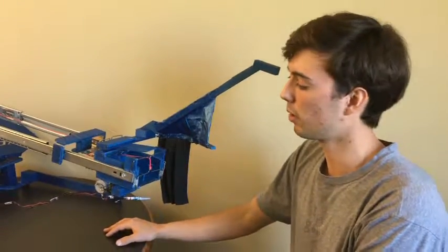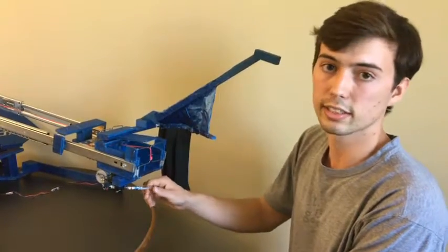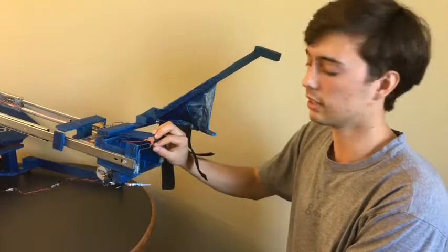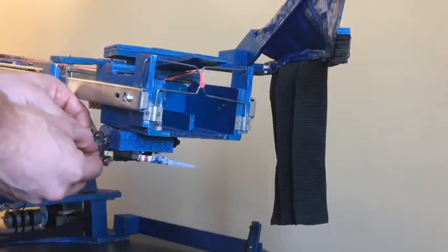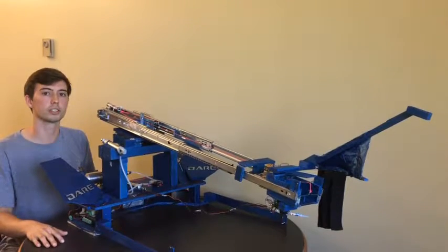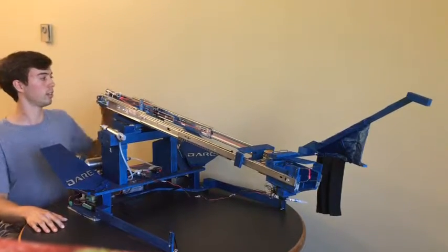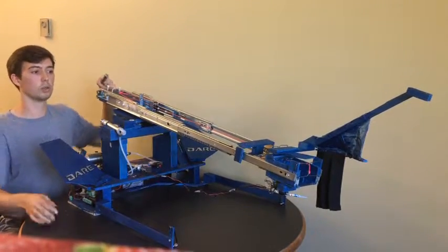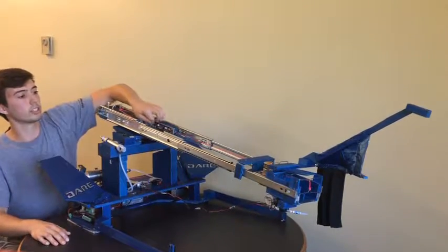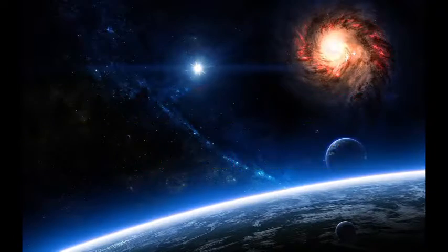The third aspect of our mountain ridge subsystem deposits the spacecraft into the safe zones. This switch detects the safe versus unsafe zones, and then a motor pulls the gate up, releasing the squash balls into the safe zone. The mountain ridge subsystem requires a lot of accuracy, so we created some systems to allow for adjustability between the tracks. One of these things is removing the weight, which slightly drops the height of the front system. The other is adjusting the string, which allows for a change in the length when reaching the cylindrical cavity.